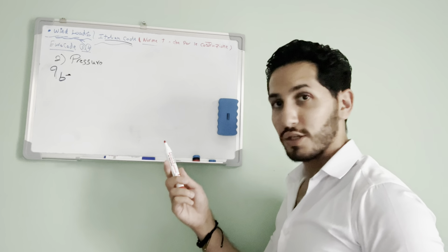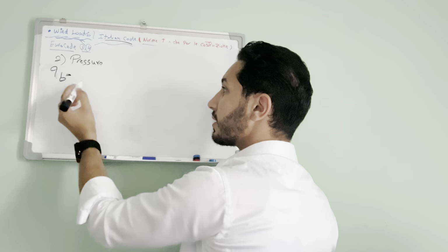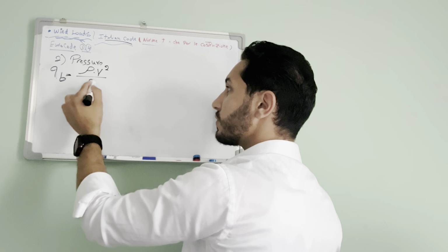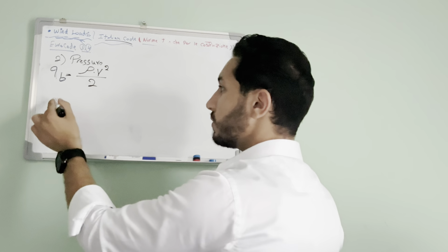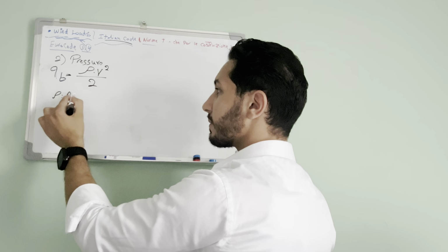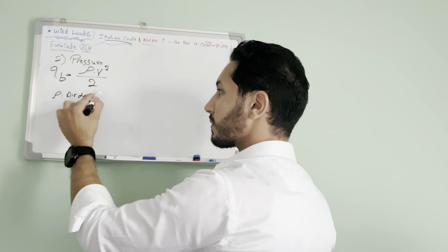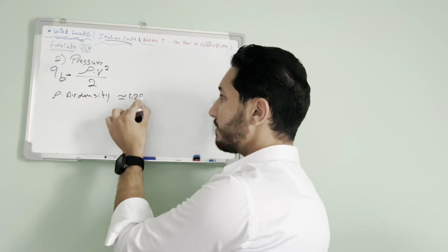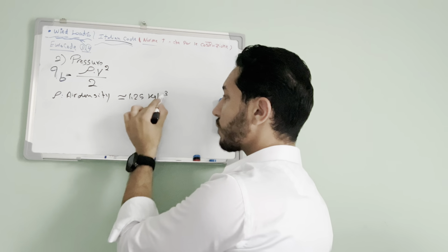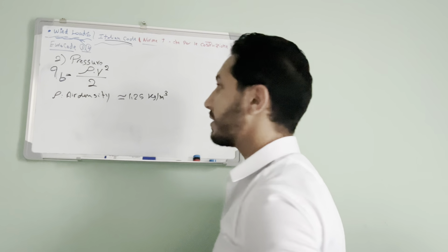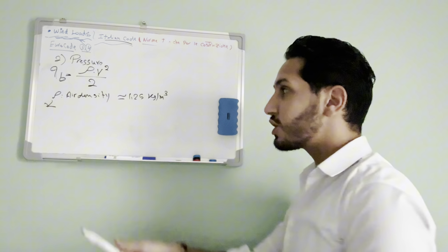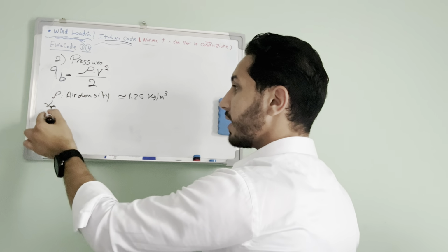It is the kinetic pressure. We have this equation here: rho times V to the power 2 over 2. The rho is the air density, and most of the time it's 1.25 kilograms per cubic meter. What is V? This is the question here. Shall we take VR or shall we take VD?